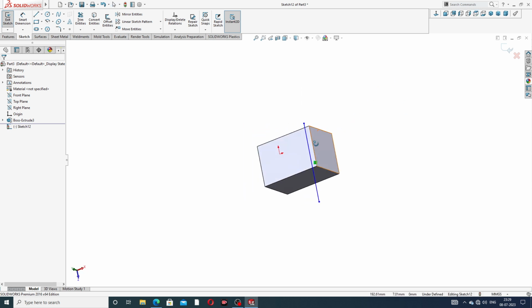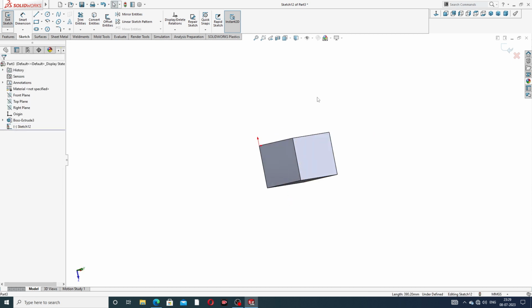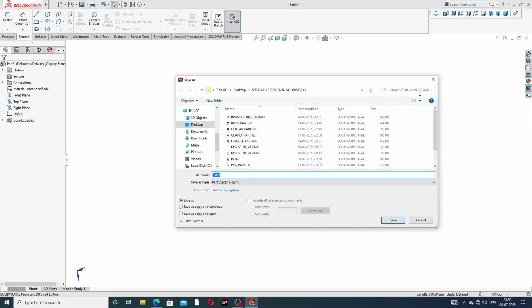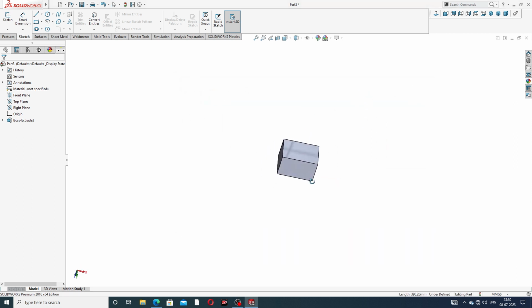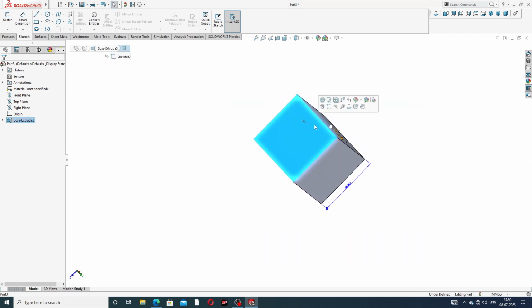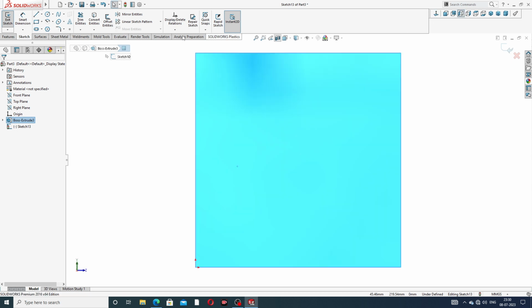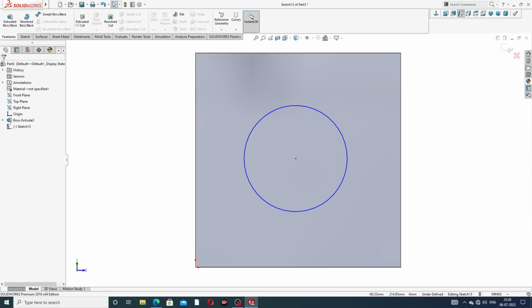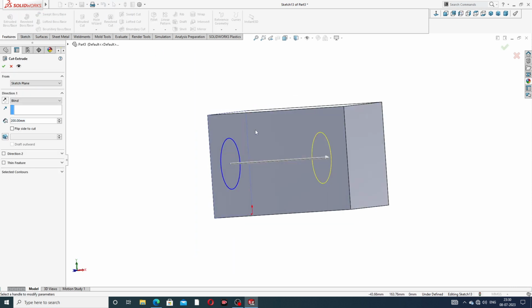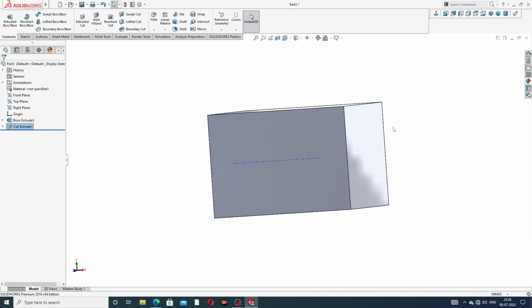Okay, this is all not used here, and some use a conical and cylindrical. Okay, at first drawing some cylindrical face. Some cylindrical face means this face is select here, sketch normal, and draw a circle, drawing this, and use an extrude cut, through all, and click OK.